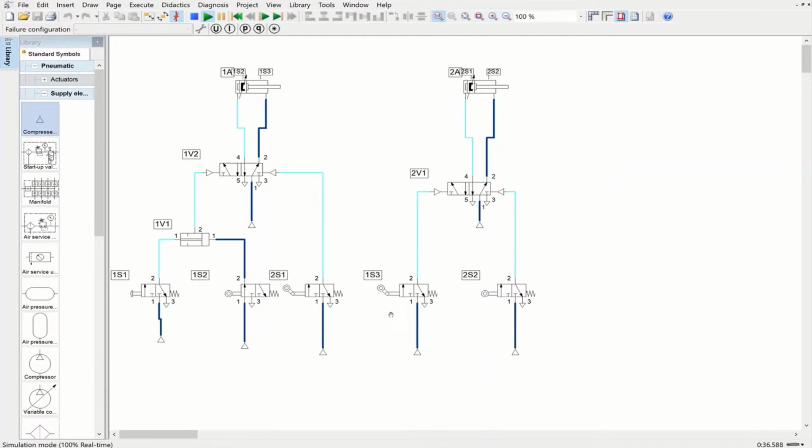As I said, for designing of pneumatic circuit, it is very important when you are dealing with multiple actuators to have a displacement step diagram handy, and at the same time having FluidSIM software or simulation software in order to ensure the circuit that you designed is working properly.